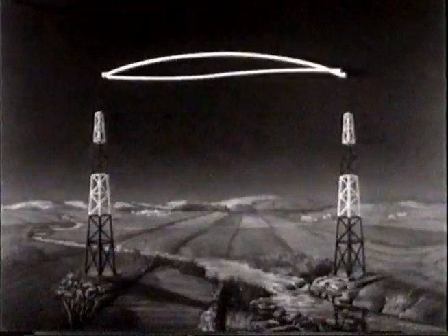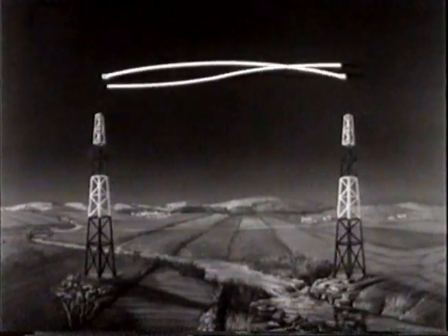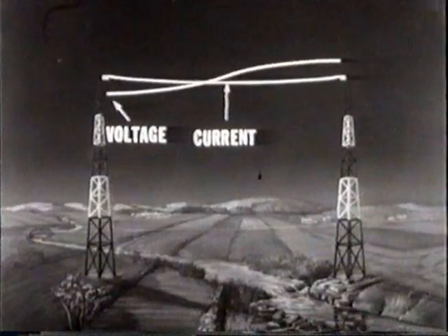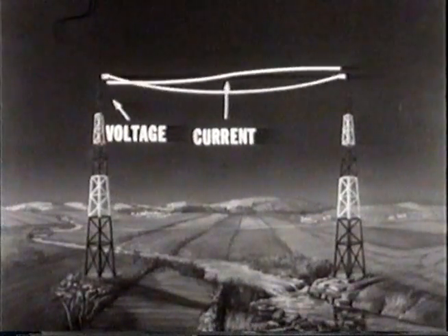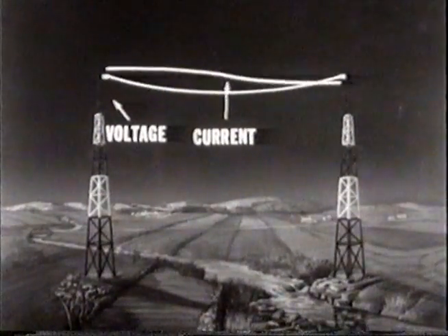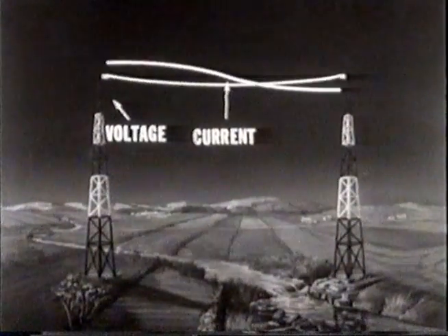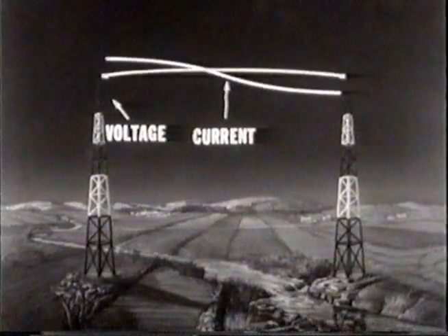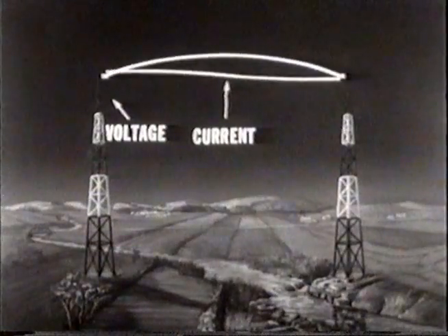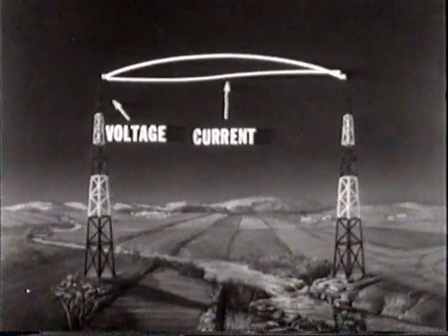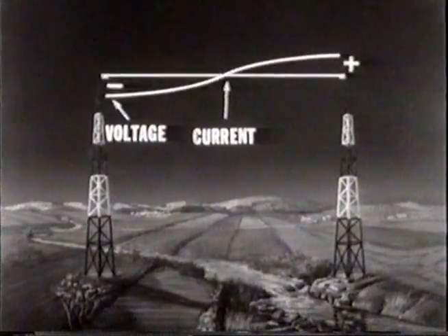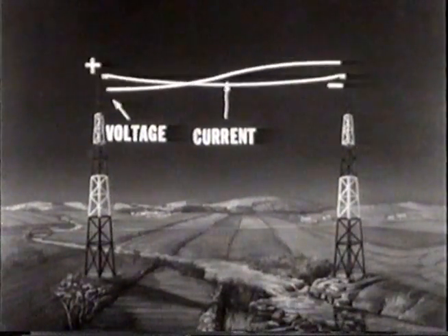We may picture the complete half-wave with both current and voltage components resonating on the half-wave antenna. When the voltage difference between the two ends is greatest, the current flow in the antenna is least. As voltage increases, current decreases, reaching minimum current at the time of maximum voltage. Each period of high voltage and low current is followed by a period of low voltage and high current.